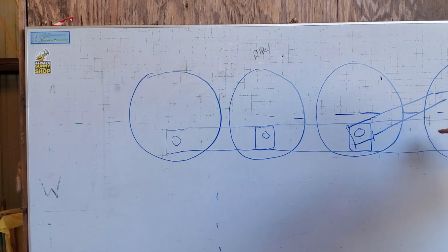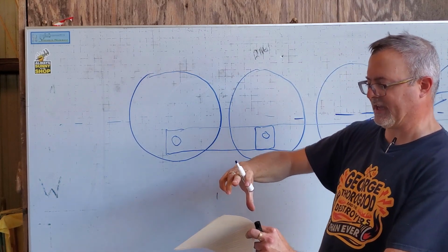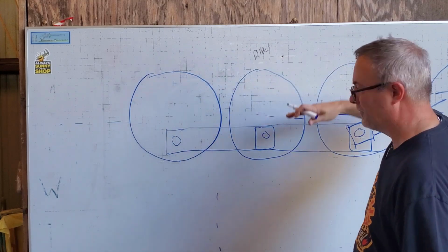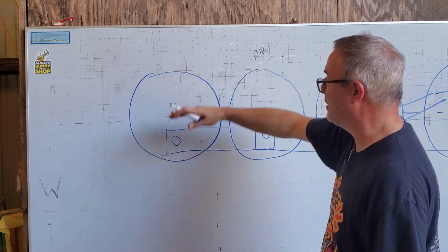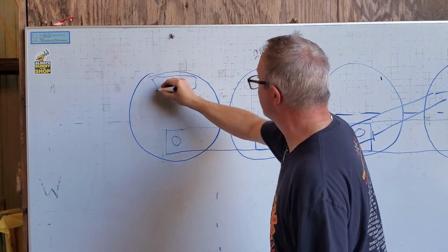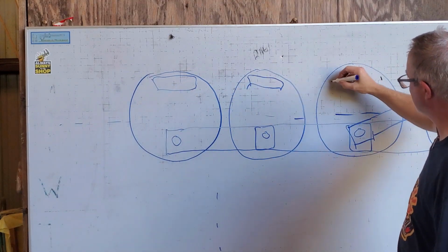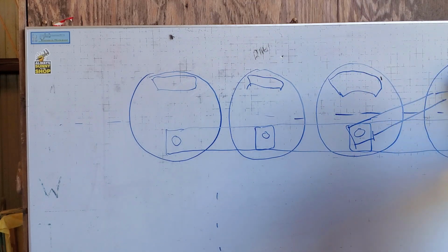Actually, these are on center, but the mass of this big side rod, you're talking solid cast iron or cast steel bars, are moving in a circle as the locomotive is traveling down the track. So all of this mass of this side rod had to be counterbalanced. And this one probably had a bigger counterbalance because it had the additional mass of the connecting rod.